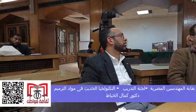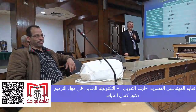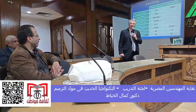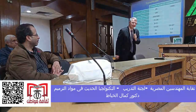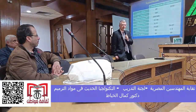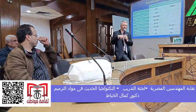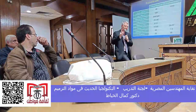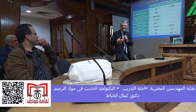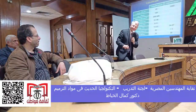This is 1960 technology, my friend. 1960. So we had a technician that used to work on this job, and he said the structural engineer was a French person, and his name was Mr. Pouce. In French, pouce means inch. 1 inch is un pouce. And he said the concrete slump should not be more than 1 inch, because if you add slump, that means you're adding water.